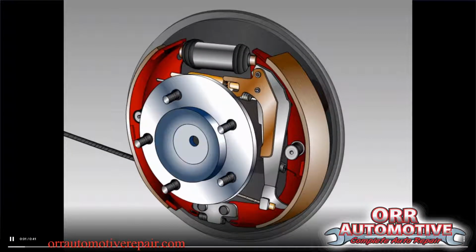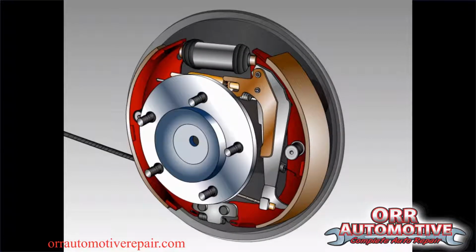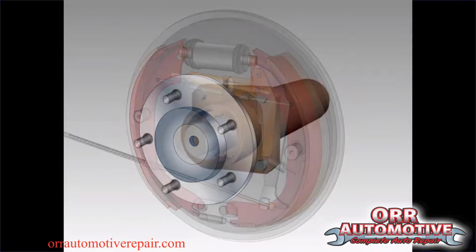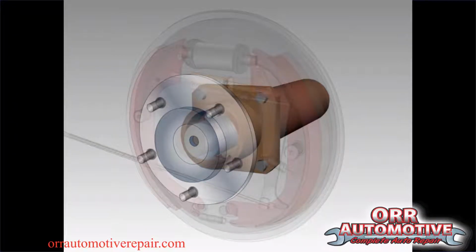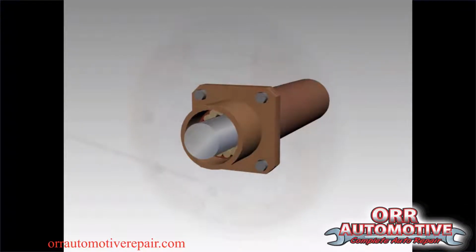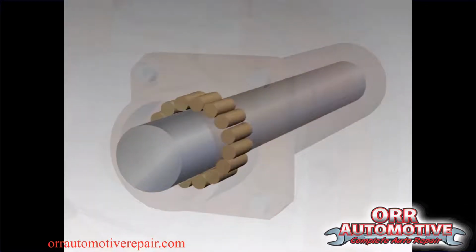The axle bearing is located at the end of the axle tube and is lubricated by rear differential fluid. The bearing also rides on the surface of the axle. When the gear oil becomes low, or if the fluid is contaminated, the bearing may not be lubricated sufficiently. This causes excessive heat around the bearing, and the heat causes the metal to become pitted or worn, especially on the axle.